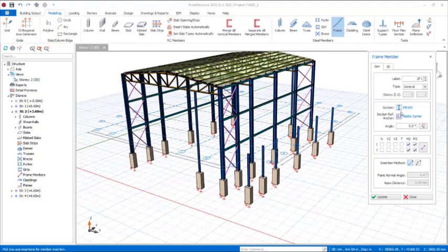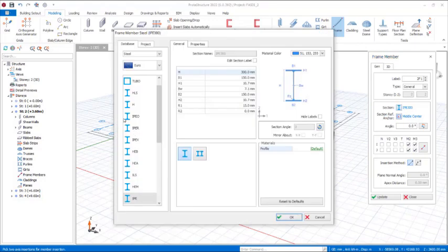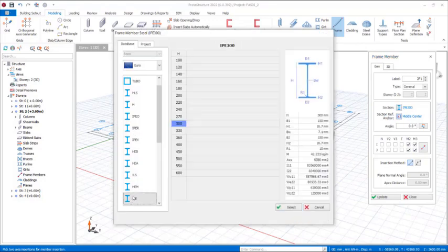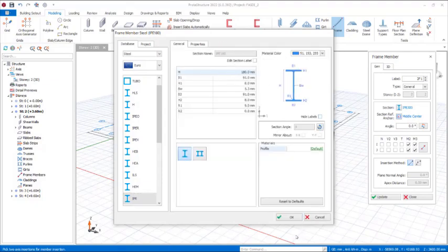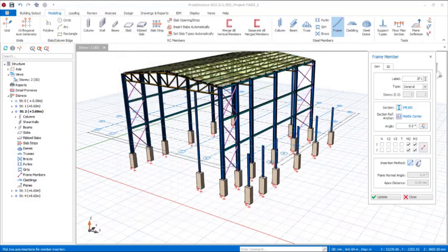All right, so after which we'll come to sections management, and then we will navigate to IP sections just like this. We'll be using IP sections 180. All right, click on the select options. All right, after which you click on the OK options. We will be using the insertion method to be this one. This is the curve insertion method.